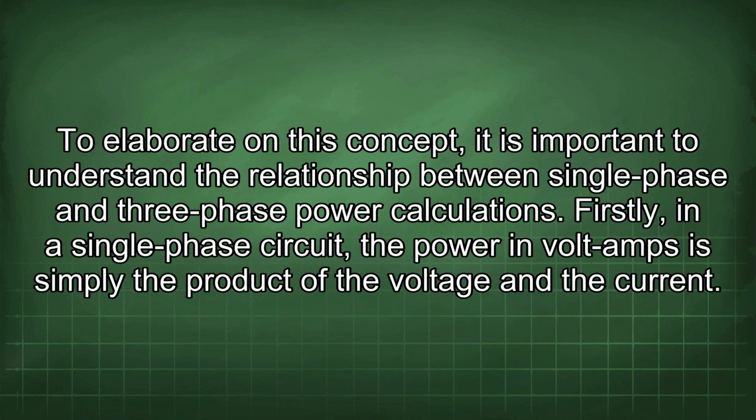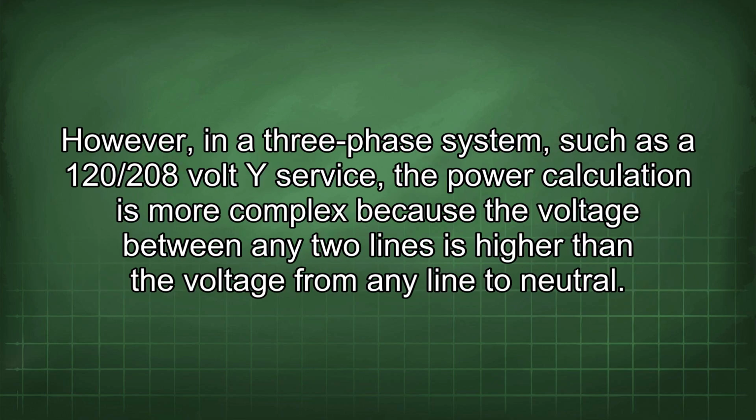To elaborate on this concept, it is important to understand the relationship between single-phase and three-phase power calculations. Firstly, in a single-phase circuit, the power in volt-amps is simply the product of the voltage and the current. However, in a three-phase system, such as a 120/208 volt Y service, the power calculation is more complex because the voltage between any two lines is higher than the voltage from any line to neutral.